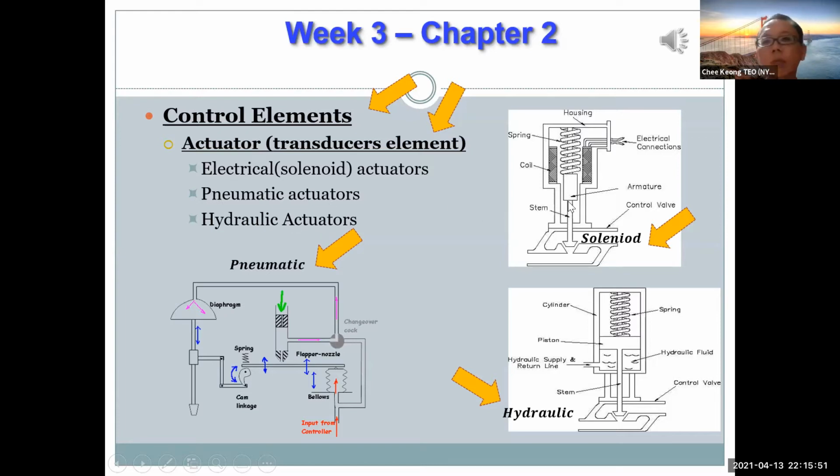Of course, the traditional one will be the mechanical type, whereby you turn the wheel clockwise or anti-clockwise to advance the piston or to open the piston. So that's the few types. Getting into the automatic kind of actuator, the plunger or the stem is basically called the actuator. So we have three types: electric, pneumatic, and hydraulics.